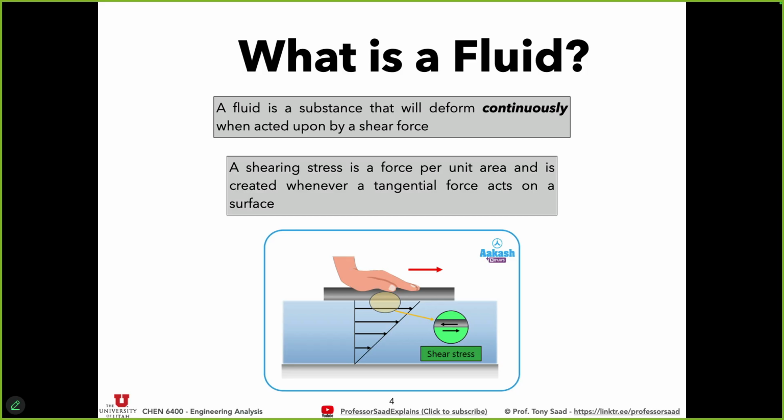A fluid does not break. It will continue deforming and deforming forever. Okay, and that's the distinction between a fluid and a solid. Now, what's a shear force? A shear force is not a normal force. A normal force is a force perpendicular to a surface. A shear force is a force that's not normal to it, rather tangent to it. So we can push this way, we can push that way, but it's not a normal force.